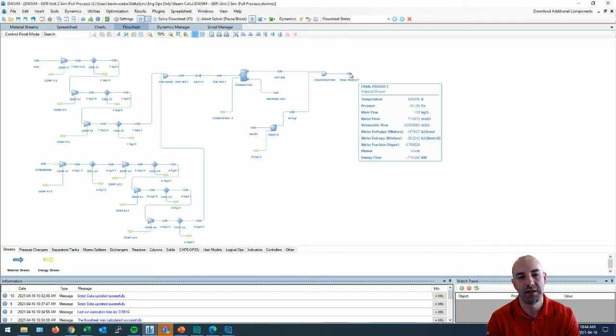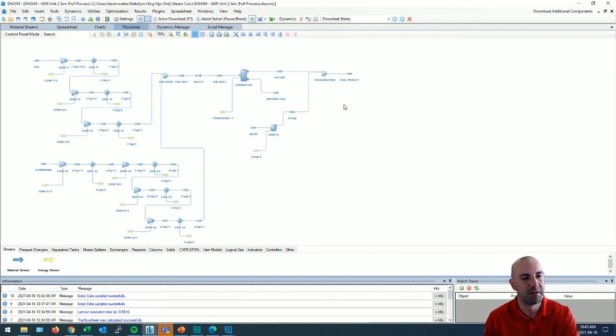This is running at around 6 MPa pressure, but our temperature is only 509 Kelvin. So when you're looking at the steam tables and you're like, wait a second, you should be 300 and whatever. It's not. It's actually around 245 degrees Celsius is our actual final product temperature. So it's maybe 60% of your saturated steam tables. That's a very good approximation, 60%.